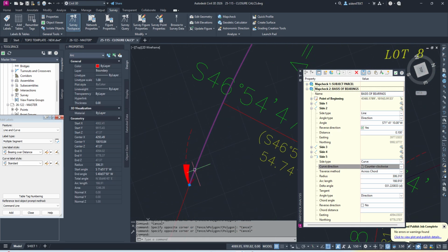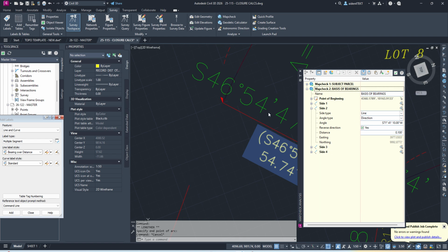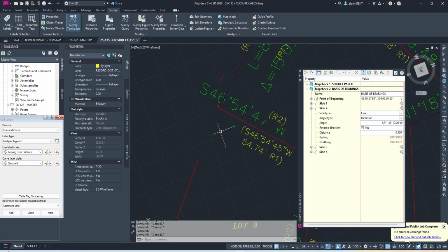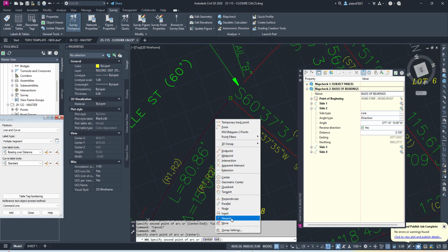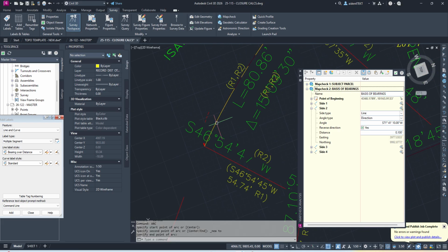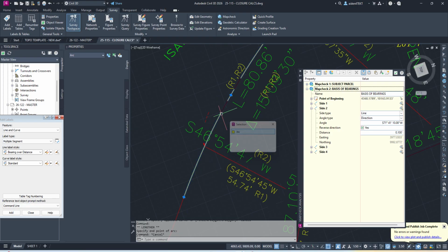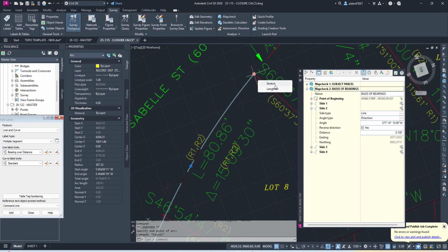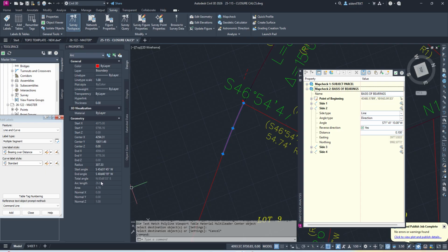What we do is you just grab this curve, lengthen, put it to there, and then delete this side here. And then you need to do an arc. Well, remember, we have to copy this over. We'll have to do the same thing to the actual record of survey drawing. Okay, and you lengthen that sucker. And you move this here. And you match properties. Okay, now it should be the same radius.